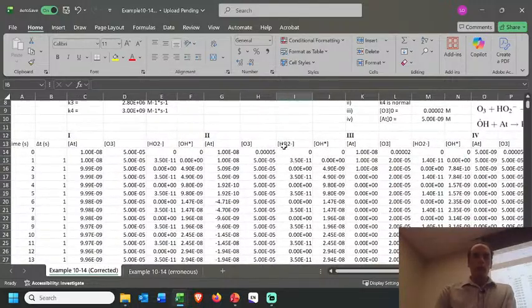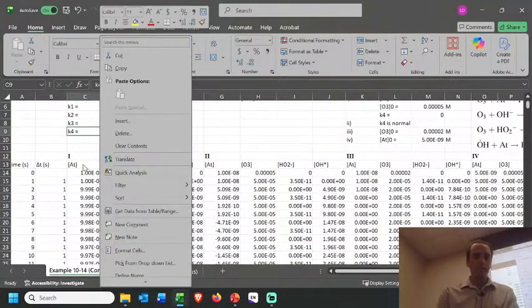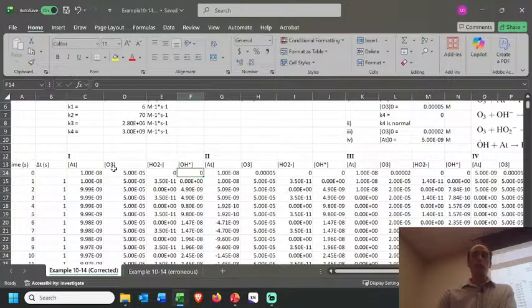At some point, I ran out of time, so I'm just going to show you the case one, what I did. I set the initial conditions according to what we knew for the atrazine and the ozone, and 0 for the reactive intermediates, which without anything happening should be at 0. From there, I calculated the different pieces.